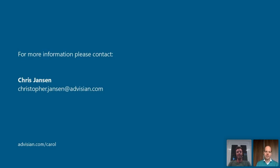Yeah, that's right. And that's a bit of an advantage in that Advisian Digital is a part of Worley, and Worley is traditionally EPC, EPCM, project management and engineering design. So we've been able to influence the projects in the project phase to look at the design of the vessels and ensure that they're as suitable as possible for the robotic catalyst removal. That means having top manways and not side manways, which is something we're looking to develop in any case. But it's also about avoiding internals that need people to go in to unbolt things, like you said there, Vincent.